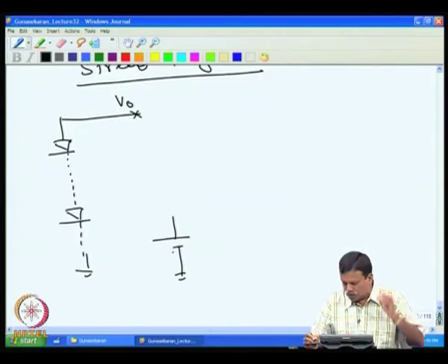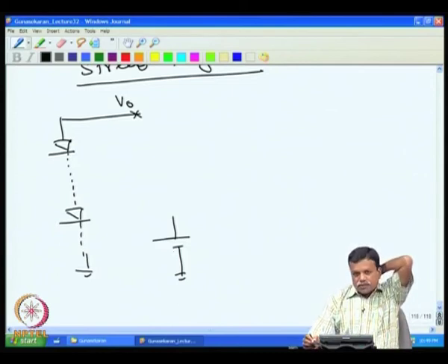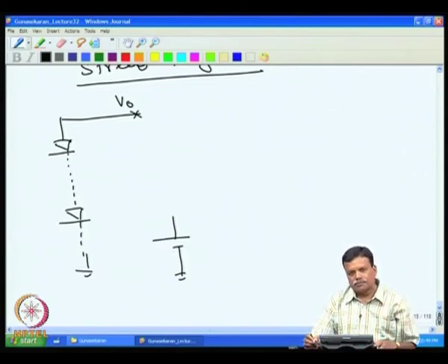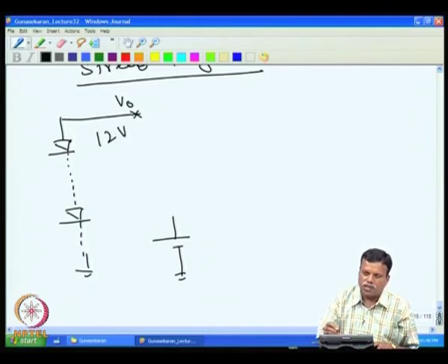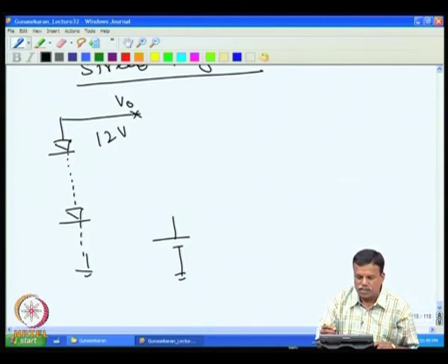We also have to do light switching. For example, if it is a 12 volt panel and the voltage is lower than 3 volt, we can assume it is already dark and we can switch on the street light.